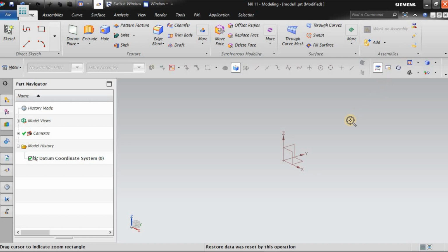Okay, so mouse button 1 is used for selection, and mouse button 2 is used for zoom in and zoom out. Suppose I am using mouse button 2 and mouse button 3 now, and I am dragging. It is used for pan. So the pan can be done by using mouse button 2 and mouse button 3. The same option is available as the pan option in the toolbar too. You can drag it wherever you want. Pan is nothing but the entire screen movement. It's not an object movement or anything. We are moving the screen from one location to another. That is called pan.